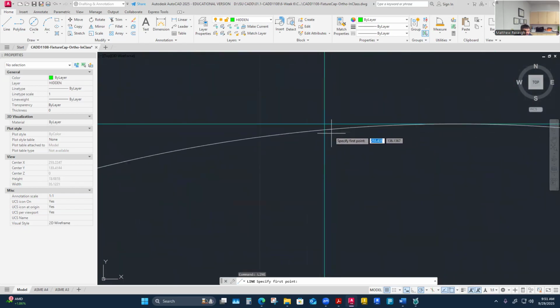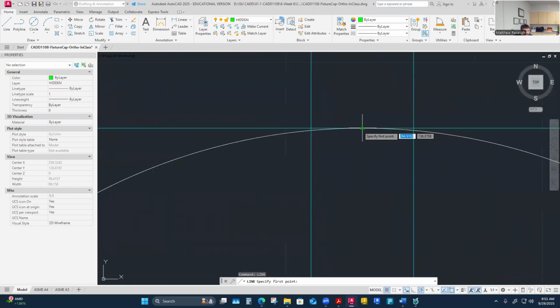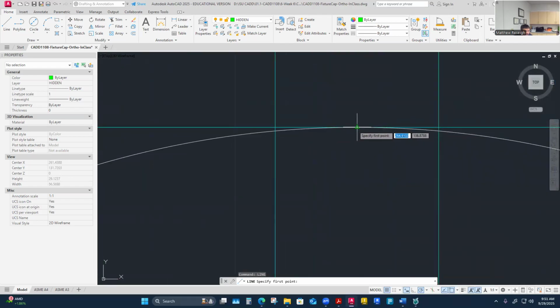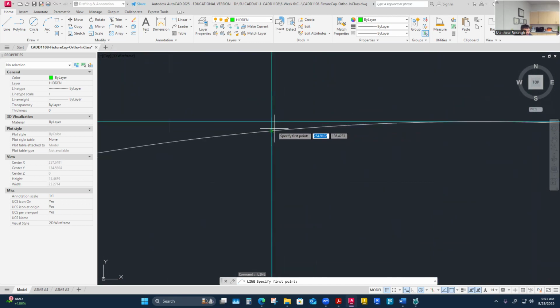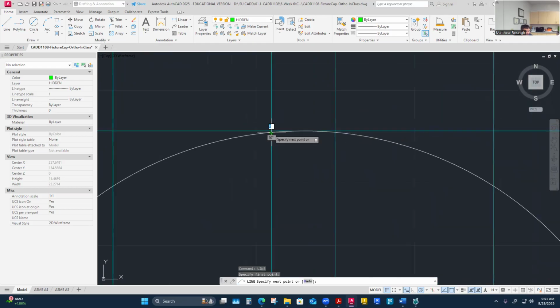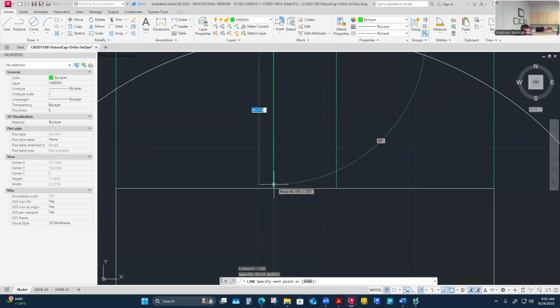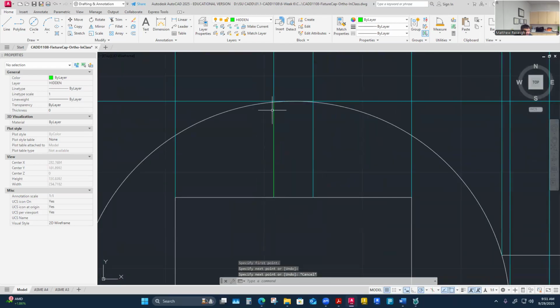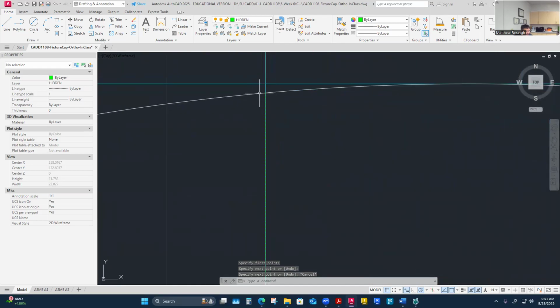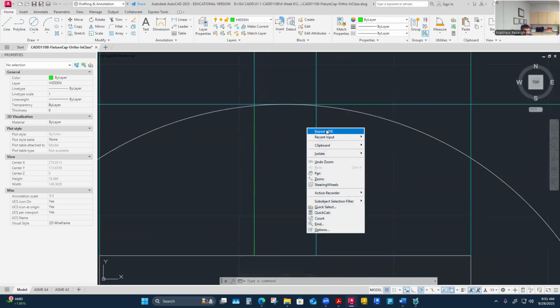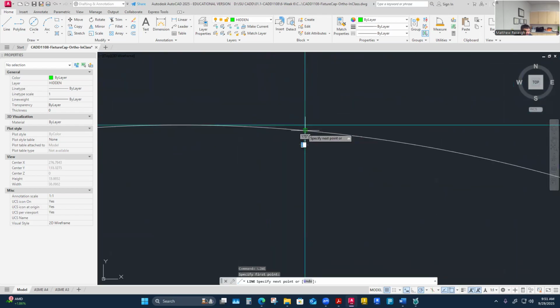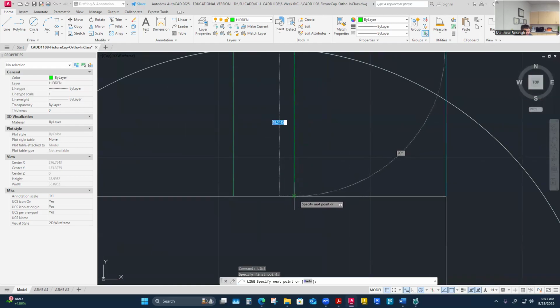I'm going to zoom way in here. Don't snap this clear to the top surface, right? Because my eyeballs on the top view only see the very apex 12 o'clock point of tangency there. Technically, this hole can't extend beyond the actual material. Hidden lines are actually visible lines, just not in my view. And so they should not extend beyond what the actual part can be here. So that one I've got to zoom in for and really pick this kind of critically here. There's where the hole goes down and through.